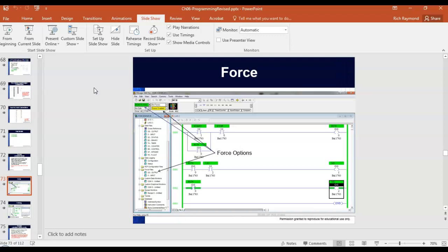So whose fault was it? It was the guy's fault that was up there, because he should have locked out everything inside that section he was working. But forcing is neat. Like I said, it's really neat. If I'm writing all these programs and it's not out there on the line yet, and I want to see if my logic is right. If this sensor energizes, this one energizes, and this one energizes, and this one energizes, is output 0 going to come on without even having my wire?